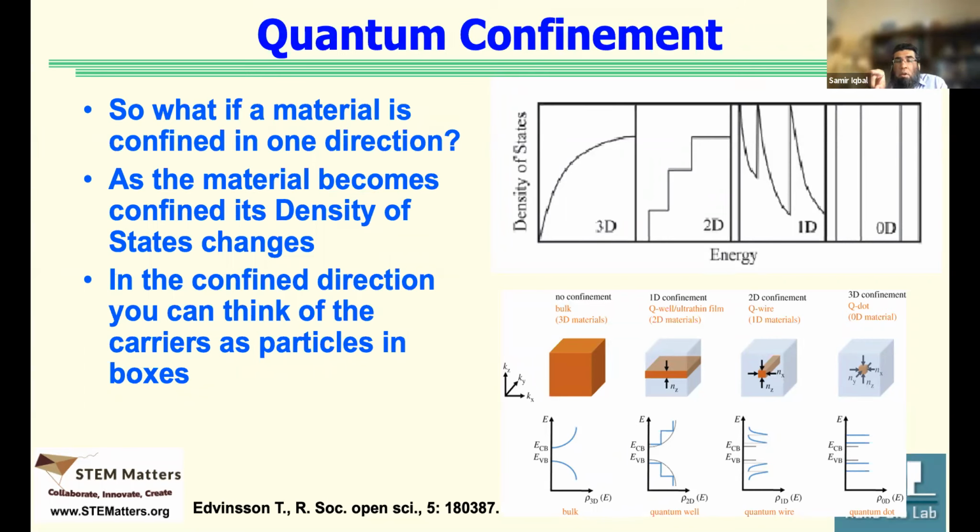So now when the electron would jump, or go from conduction band to valence band, it's going to emit only one wavelength because it is coming through a well-defined change in energy. Unlike 3D material, where there are a bunch of density of states, so the electron may be coming from other energy states, hence giving other wavelengths as well. But in a quantum dot, it can only emit one wavelength because the states are very well defined, because we have restricted physically for that electron to have multiple states.